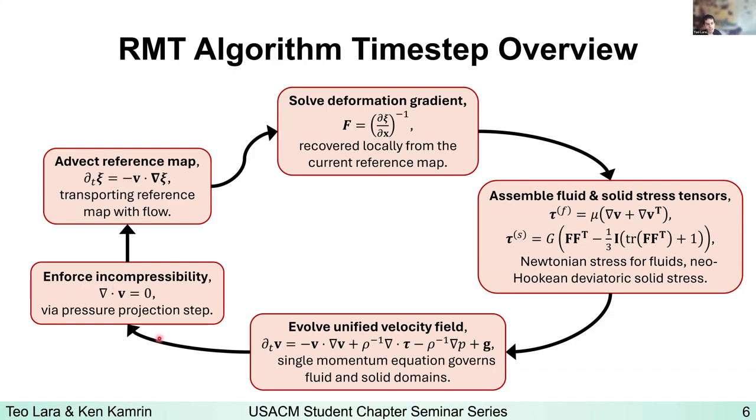Now, these 3 bottom steps is just your standard incompressible Navier-Stokes solver, and just add on this reference map paired with the solid stress to incorporate solids into our simulation.